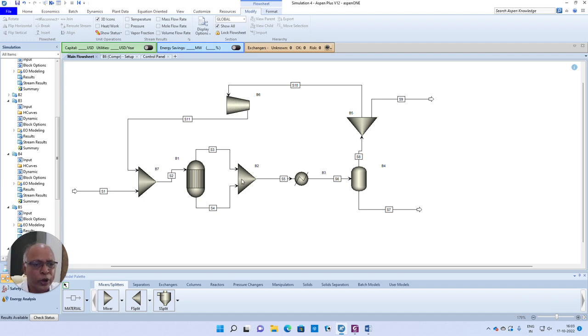The moment you solve B2, we compare the result with the initial approximation for S5. Compare these two successive values, and if all the variables come to a convergent solution, then the iterative process stops. Otherwise, we start with fresh guesses for the tear stream, and the next iteration proceeds.